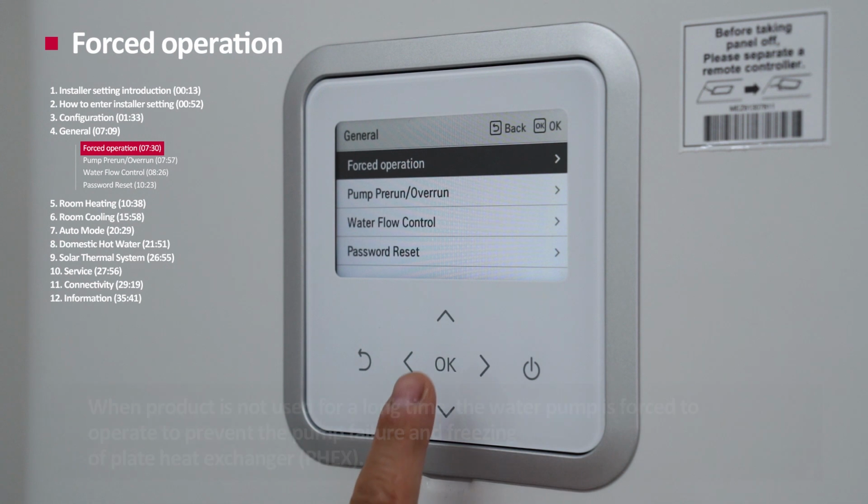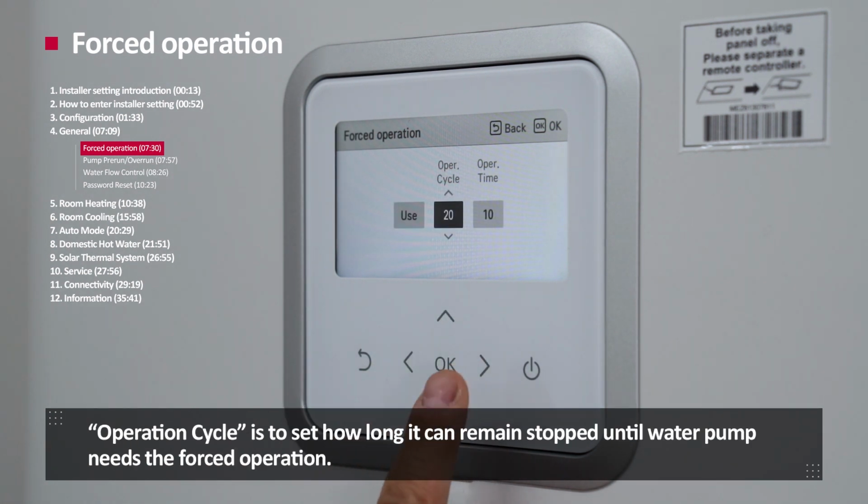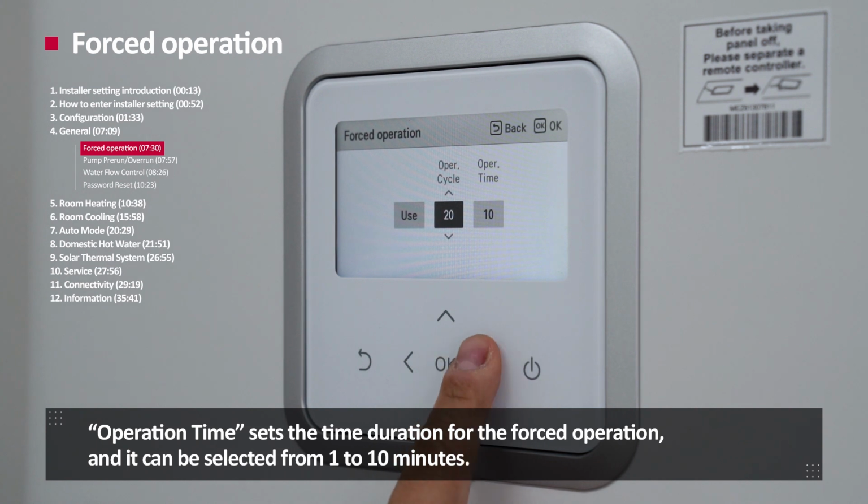Forced operation. When the product is not used for a long time, the pump is forced to operate to prevent pump failure and freezing of the plate heat exchanger. Operation cycle is to set how long it can remain stopped until the water pump needs the forced operation. Operation time sets the time duration for the forced operation, and it can be selected from 1 to 10 minutes.